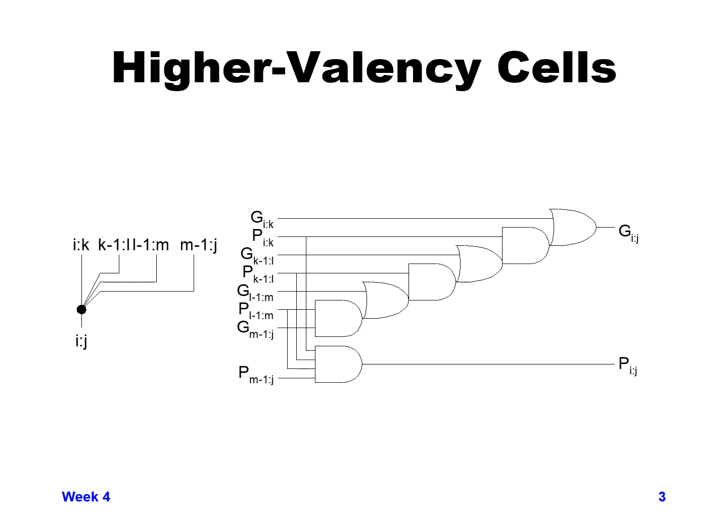So basically we're doing an AND-OR function for the total number of inputs that we have, and you could plot this out in terms of transistors, what you would need in order to make this. But you'll definitely find that this type of structure, with the number of series and parallel devices, will add more capacitance, and series devices will add more resistance that you need for your drive strength. So this gate is definitely going to be a lot slower than you would get from just a single 2-input XOR or AND/OR function.